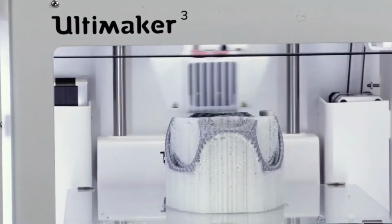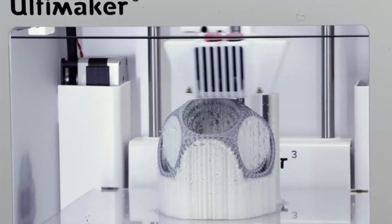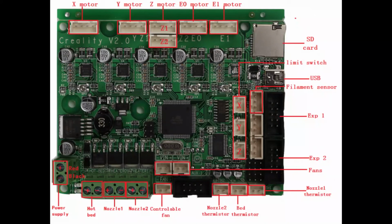When we select and activate the print job in the interface, this action triggers the control board to start the printing process, unspooling a series of actions across the electronics, from diverting power to preheating the heated bed and toolhead, to reading through the initial pre-print commands and settings in the G-code file or onboard in the firmware. The interface only plays the role of the messenger. Now the real orchestra tunes up and is poised for action.